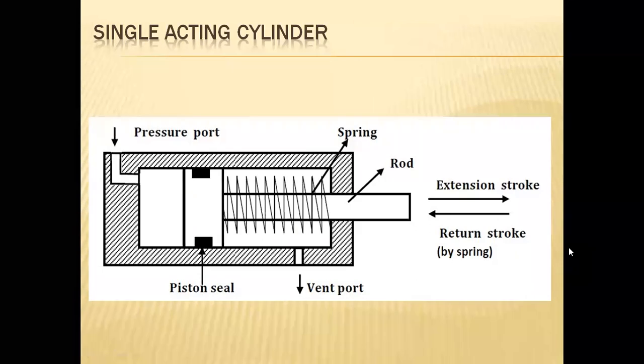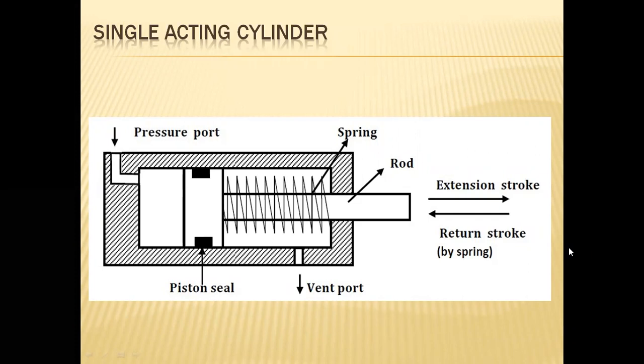Here in the single acting cylinder, there will be only one movement which is energized by the pressurized fluid or gaseous medium. In the case of this hydraulic system, we'll be utilizing only the pressurized fluid, right? That fluid may be of different kinds of oils, which vary in viscosity levels.